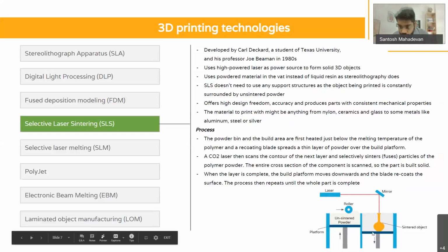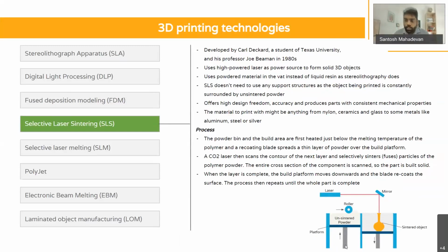Okay, to start off, this build platform has its surface right on the top, and this reservoir platform has its surface right at the bottom. So you're going to have some amount of volume over here, and you're not going to have any volume over here. The idea is to push this platform up the height of the layer.